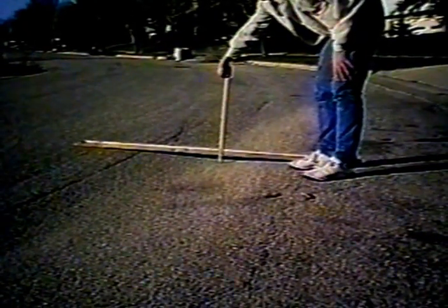This can be a safety hazard, obviously, for the driving public, and it's an indication of surface problems probably related to the quality of the mix design and maybe the construction process. That is, if you don't get adequate compaction initially, you have more compaction under traffic, and you see slight surface rutting beginning to develop. Now, that can become more severe.